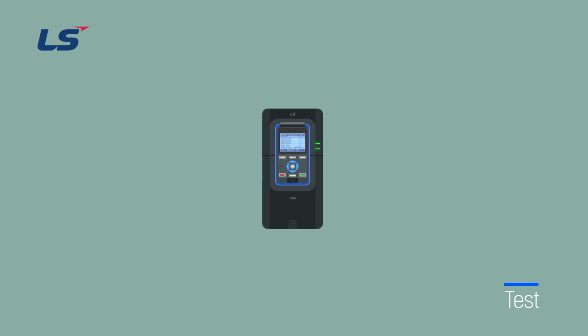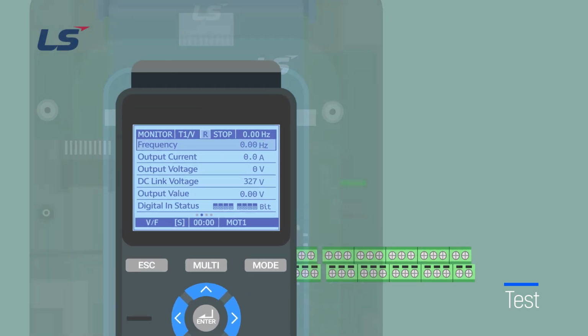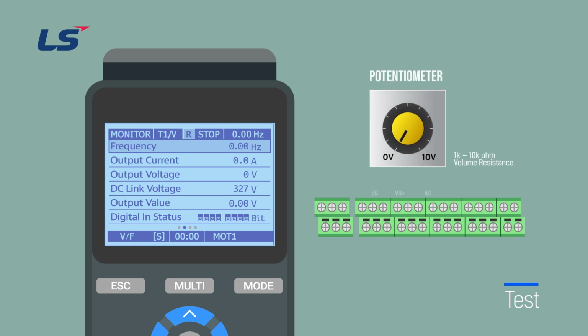Next, we will proceed with testing under the parameters set earlier. Wire a variable resistor to VR+, AI1, and 5G terminals using internal power, and rotate the variable resistor to check if the target frequency changes. Below 2 volts, the frequency command will be 0 Hz. Above 9.5 volts, the frequency command will be 60 Hz.